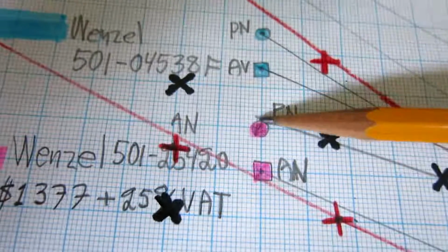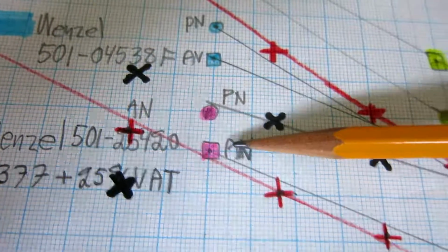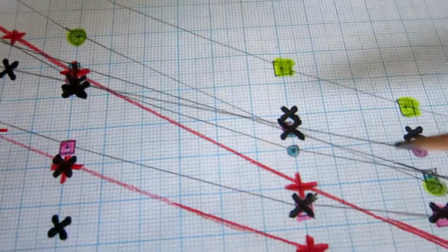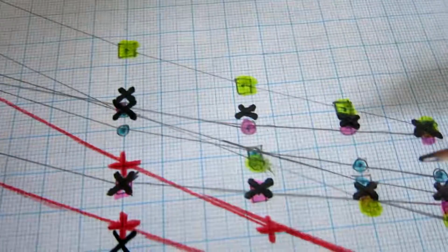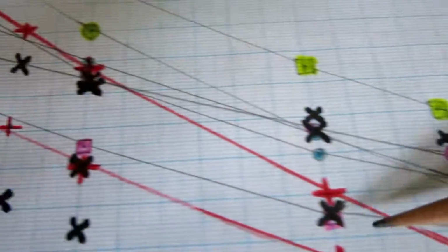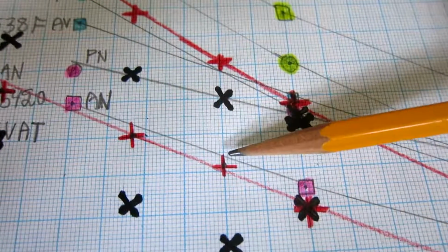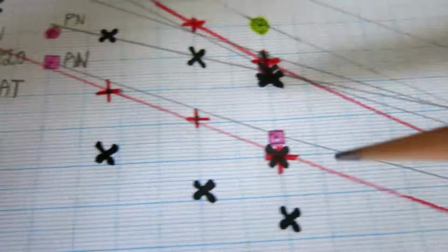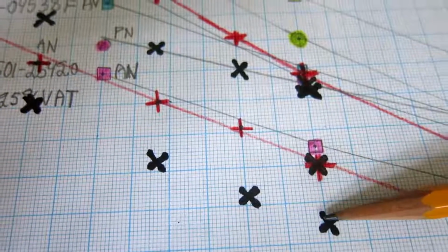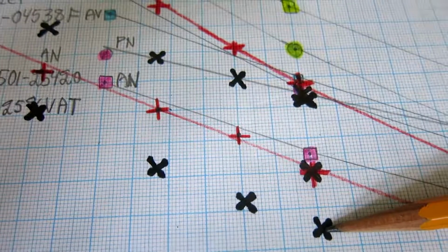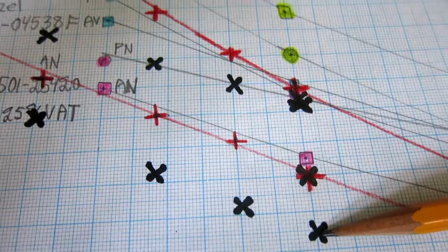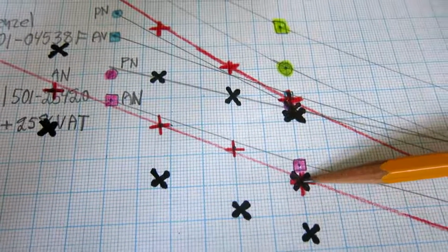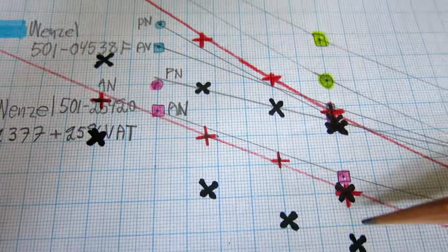You can see here phase noise, amplitude noise, these curves. The black crosses are the measurements I have done now. The ones at the wider bandwidth with a larger FFT fit very well on the old results, while the result I got now, the last measurement on a smaller transform size, indicates a 3 decibels better performance for the amplitude noise. I don't know the reason for that.